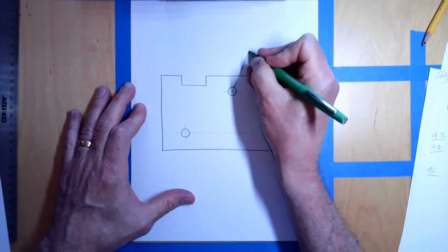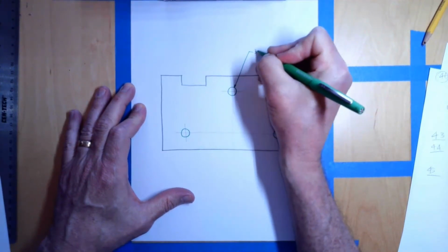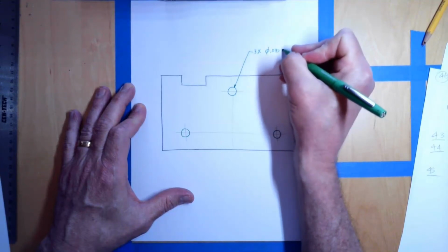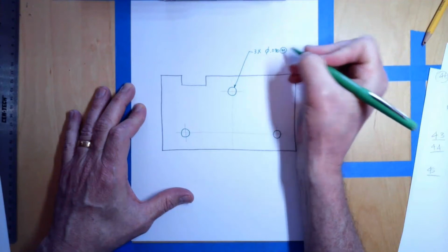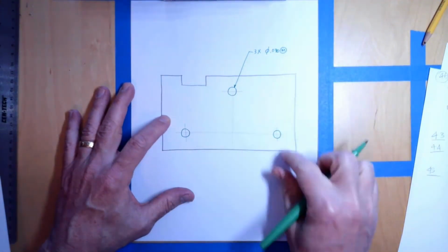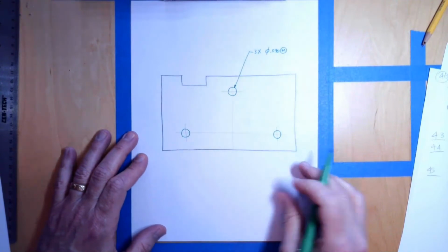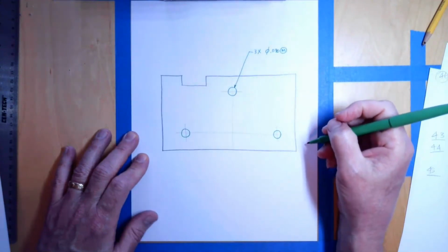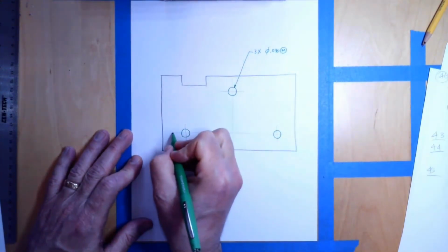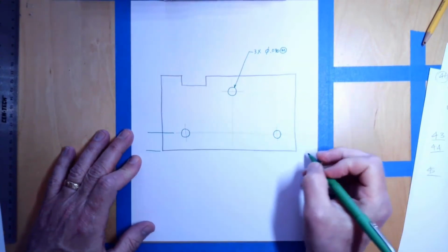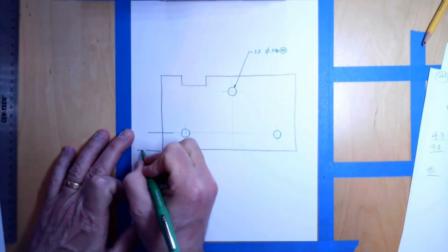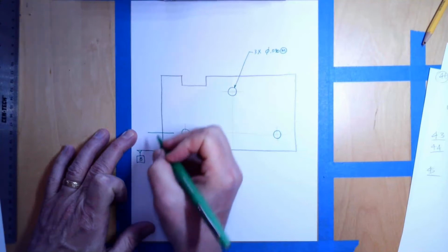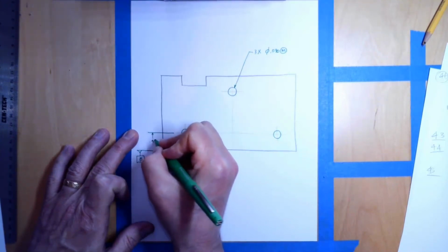Now, the size of each one of these 3, these are 3 times a diameter of .030 at MMC, all 3 of those holes. Where are they located? Well, they're located 90 degrees relative to A. A is the bottom surface of this. From B, remember, this is B. I'll put this over here, right here. This is B. So from B, this is going to be 0.450.